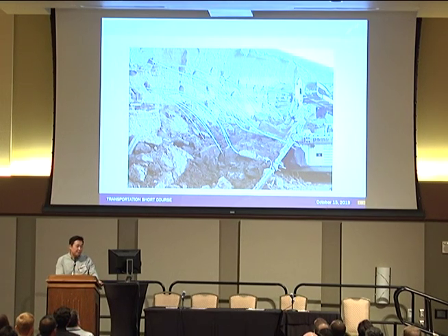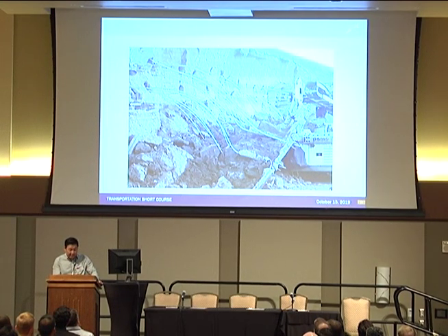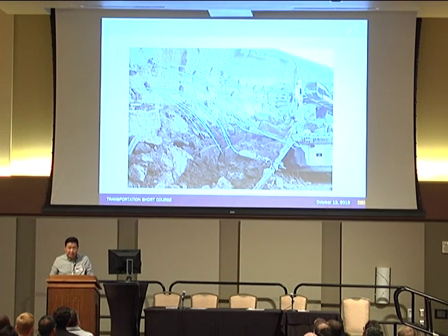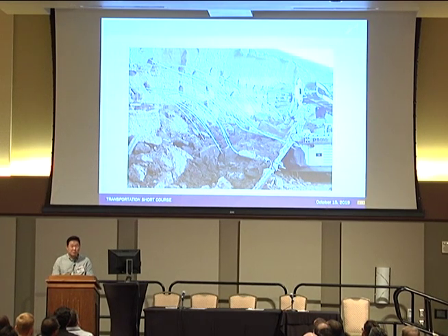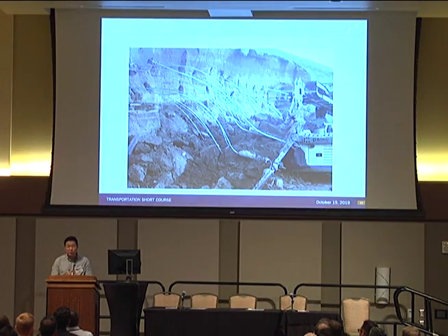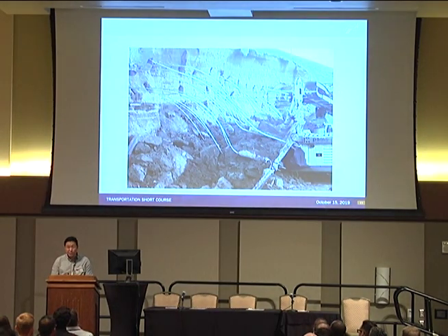After installing 3 or 4 rows of soil nails, it failed, and as you can see, out of 30 feet, the grout is only 4 to 5 feet. So it is a combination of multiple issues, like the grout thickness and also poor construction.